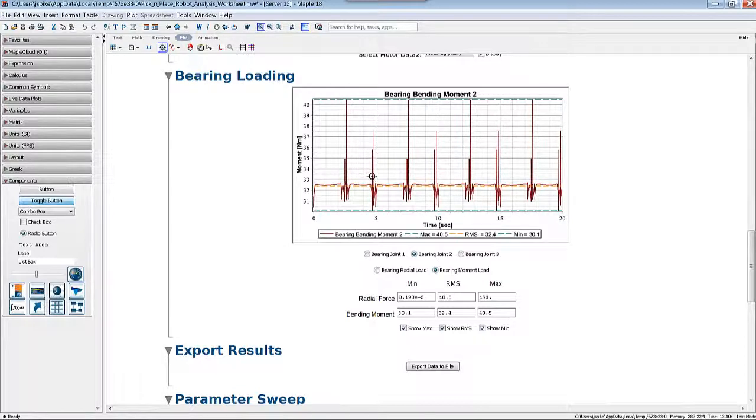These two points relate to the two ends of the desired path that the robot actually performs in. During the pick and place operation, where the end effector goes up and down, is a particular time where our bending moments may incur large magnitudes and spikes as the end effector is actuated. These could be areas where our bearings may become overly loaded, and changes in the design either through making sure our bearings are stronger or perhaps changing the way that the end effector is actuated may need to be considered in the design process.